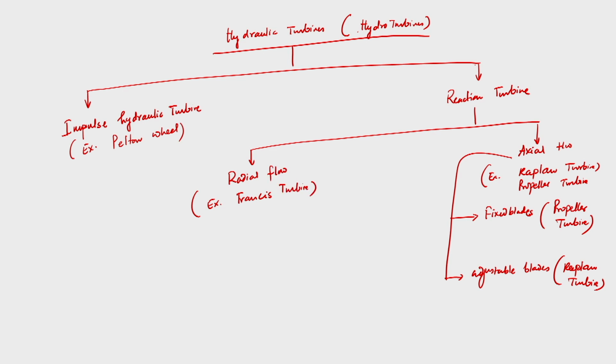Now, we will slowly discuss what an impulse turbine is and what a reaction turbine is, why we call it an impulse turbine and why it is a reaction turbine, it is very important. An impulse turbine is a class of hydraulic turbine which has one or two fixed nozzles, in each of which the fluid pressure is converted to the kinetic energy of an unconfined jet. Whenever water falls from the reservoir, it initially enters the nozzle.